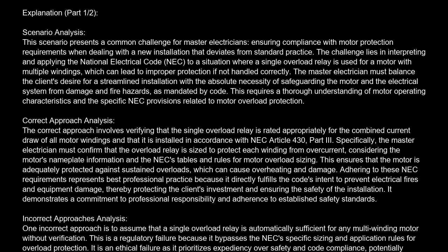Incorrect approaches analysis. One incorrect approach is to assume that a single overload relay is automatically sufficient for any multi-winding motor without verification. This is a regulatory failure because it bypasses the NEC's specific sizing and application rules for overload protection. It is an ethical failure as it prioritizes expediency over safety and code compliance, potentially exposing the client to equipment damage and fire risk.